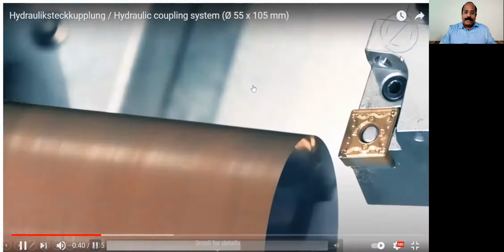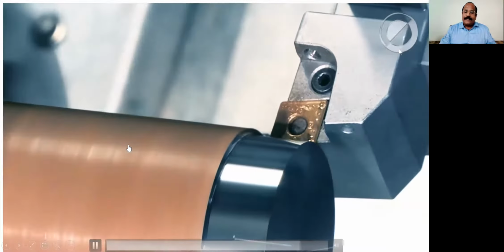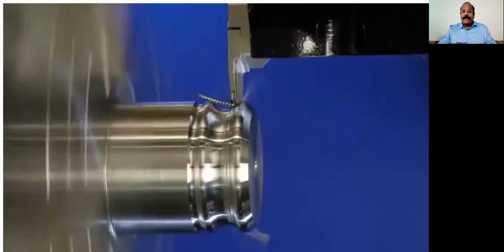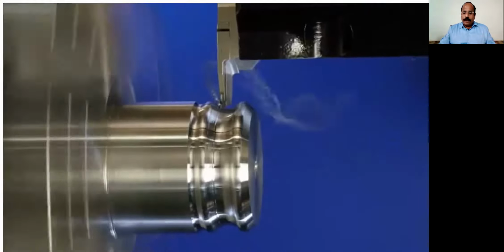Okay, for cycle time calculation, in the OD operation, how much length you cut determines your cycle time. So this is a profile turning we can do. Various profiles can be turned internally, externally, but you have to make a proper tool selection which will not foul the component while doing the operation.